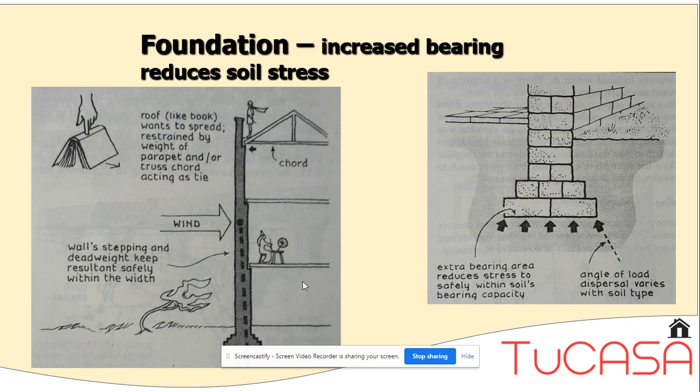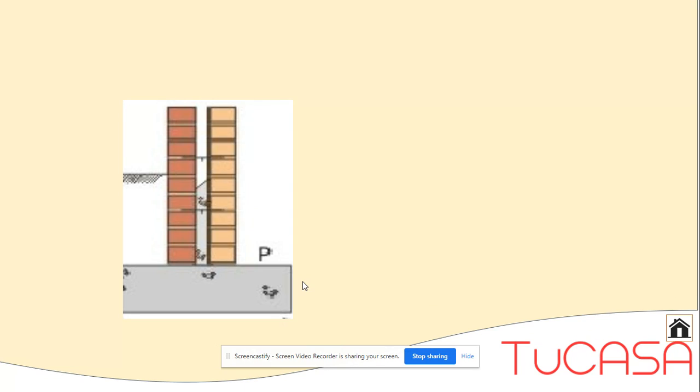Bylaws were introduced in this country in the late 19th century, which evolved into the building regulations of today, and you can find these incidentally on a website called the Planning Portal, where it gives you guidance on planning regulations and also the approved documents under the building regulations as well. Over the years, foundations have evolved in different materials, concrete, stone, brick, and the idea is to transfer then safely the loads of the building down to the ground so that the building remains stable.